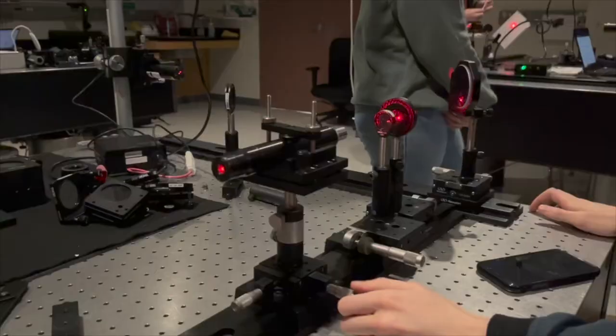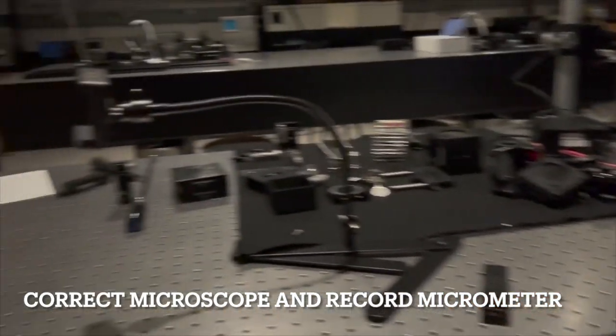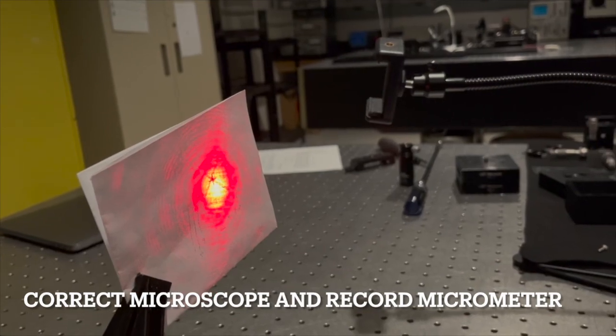We scanned across the mask again and then adjusted the microscope position perpendicular to the optical rail until the beam was once again centered on the crosshairs and recorded that absolute microscope position with the micrometer for each hole.